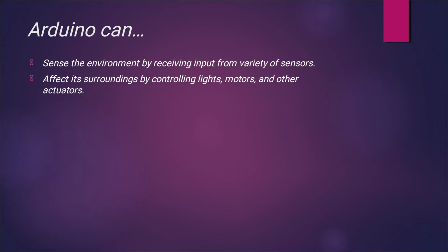Photoresistor: the value of the resistance depends on the incident light density, that is 1 kilo ohm at light, 10 kilo ohm at darkness. Now photodiode: the current is controlled by the incident light density. And phototransistor: the base emitter junction is controlled by the incident light density, and it has an amplification effect.